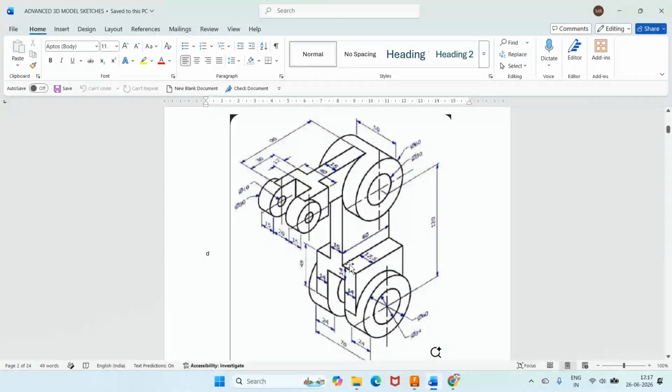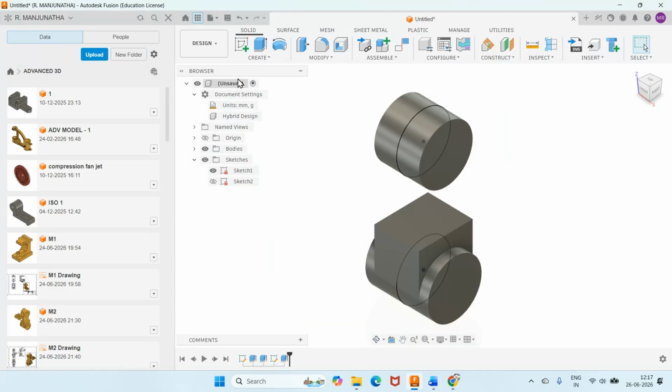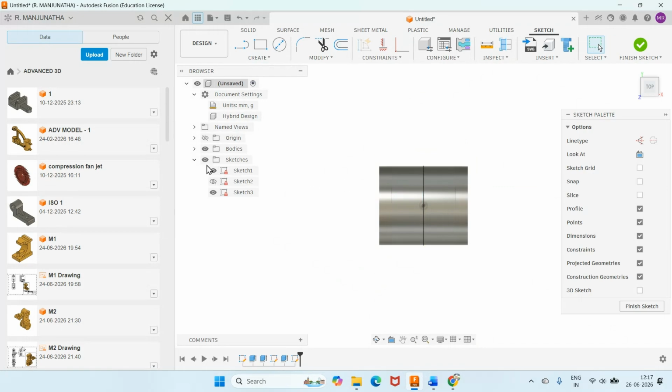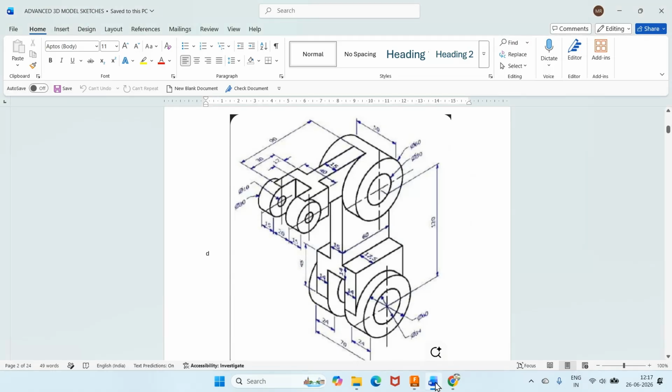Similarly, I want to go for the top plane and create this rectangle and extrude this. I will just go for a sketch, click on this top surface. Now I will go to bodies, project and click on this particular body and say OK. Now I will disable bodies. In this, what I want is the entire rectangle, that is this rectangle, which is 15.